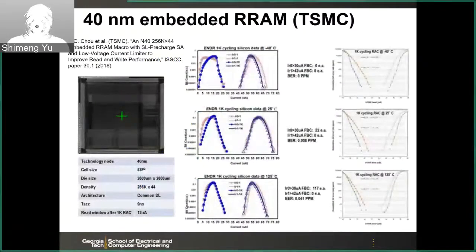But unfortunately, after the publication of the 32 gigabits from SanDisk and 16 gigabits from Sony and Micron, I believe those companies gave up. The major reason is the variation or reliability from the product perspective. It's very hard to control. Yield, reliability, and variability are the major concerns for large capacity RRAM chips, like 16 gigabit or 32 gigabit.